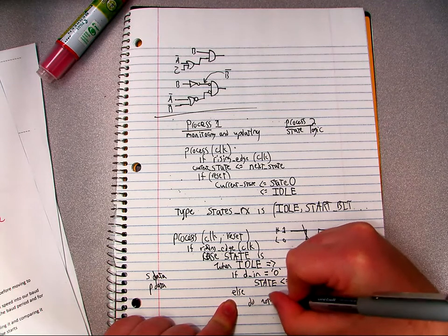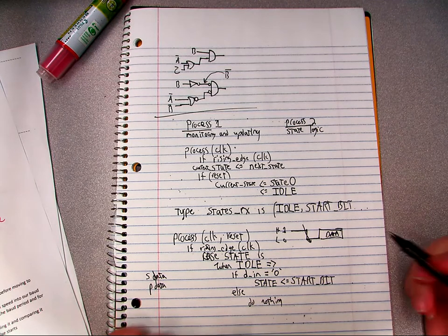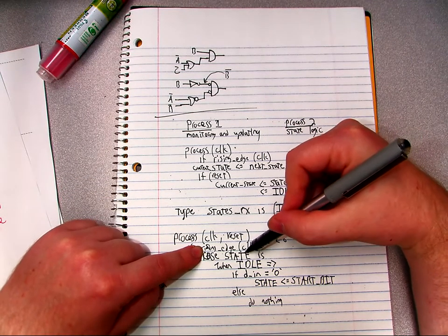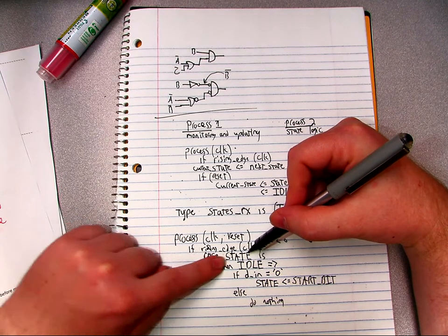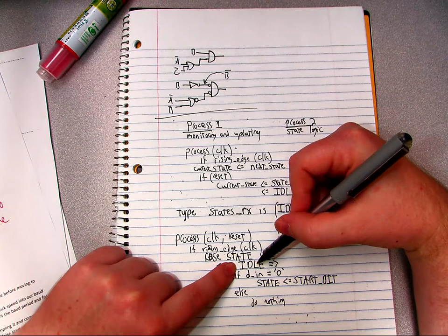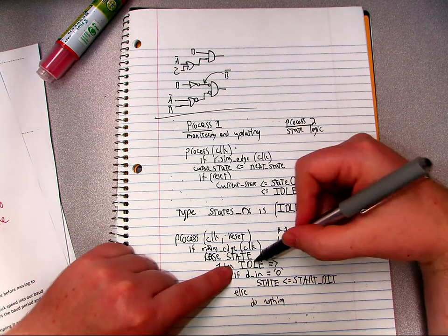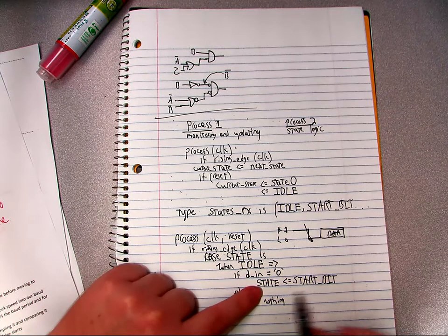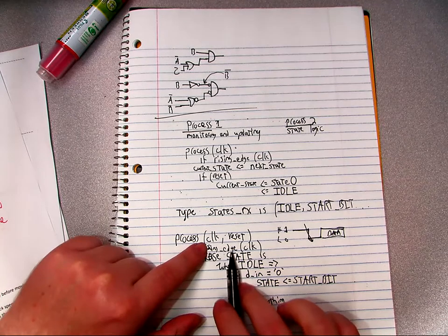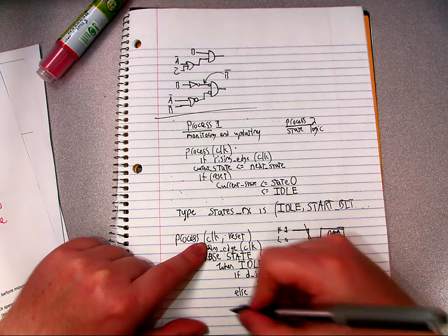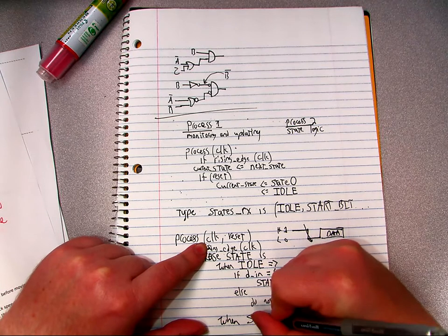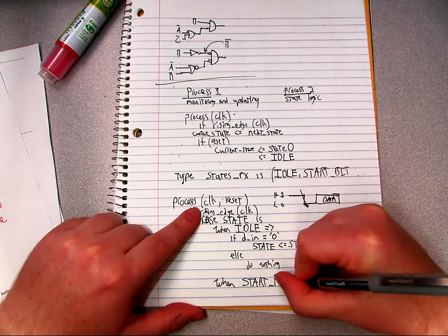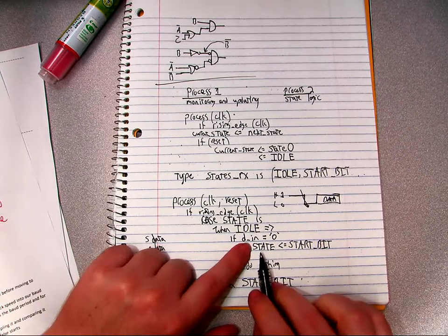Well, that's easy, right? And what's going to happen is it's going to come into here. The rising edge of the clock is going to happen. State is idle. If, right, so we're hanging out in this idle. If the data is still 1, nothing happens, and on the next clock cycle, we're still in idle. If it has dropped to 0, state is now defined as start bit, and so on the next clock cycle, instead of being in idle, we're going to be inside this when start bit, right? Because now state is start bit, because I've defined that.